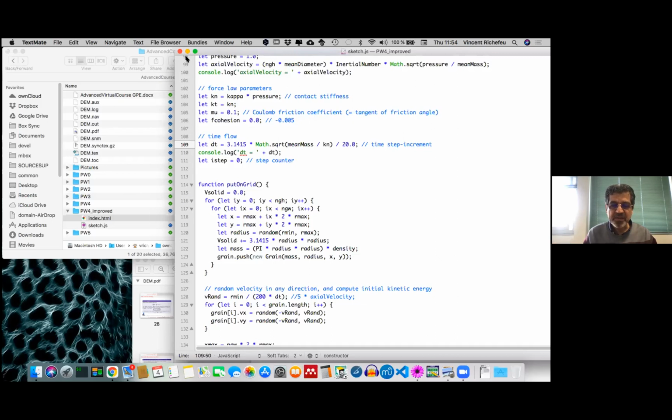I think it was published in 2012, Nicolas Estrada, and it shows that for a given value of mu r, you have an angularity corresponding to that value. And if you use that value, then you get exactly the same value of the shear stress. So it's quite detailed. It's a good way.